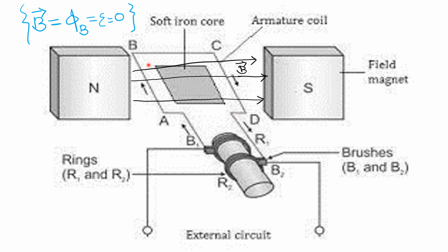So the armature basically produces an induced electric current inside the alternating current generator by its rotation. So in an AC generator, the armature rotates along its own axis. Whenever current is produced inside the wires of the armature, the wires are connected with two rings. These two blackish ones represent the rings. These are called slip rings. They are made up of copper.